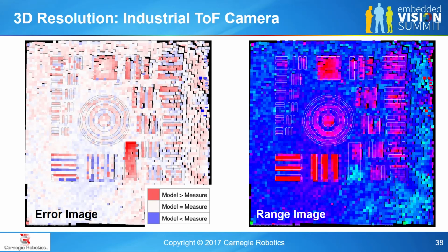But again, when you start thinking about how these sensors work, it makes sense that it's emitting IR light, it's hitting that ramp. The ramp is matte, but still some of the IR energy is being reflected down away from the camera instead of towards the camera. That is reducing the amount of signal that the time-of-flight camera has to see the ramp and making it more difficult to see that kind of geometry, and it's just blending in with the background as a result. You also see that there's no difference in horizontal versus vertical resolving power on these cameras. The horizontal and vertical bars are basically identical in terms of performance and accuracy, and there isn't the webbing that you see with the stereo cameras.